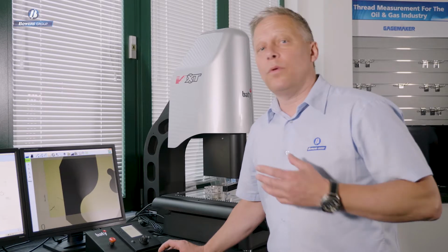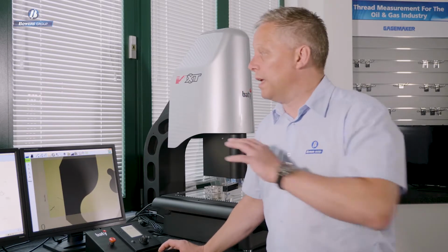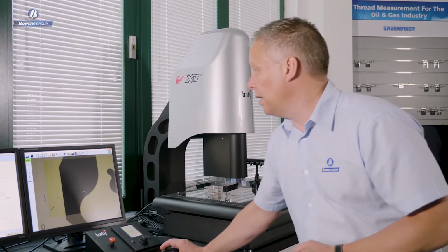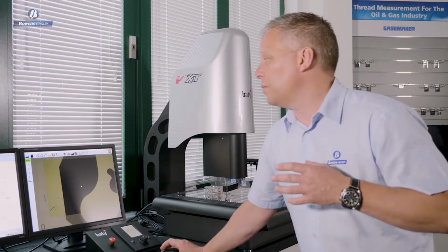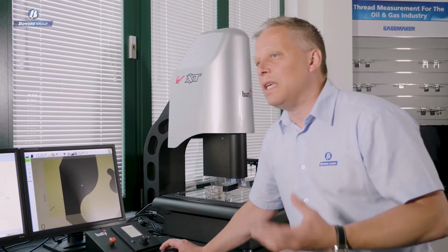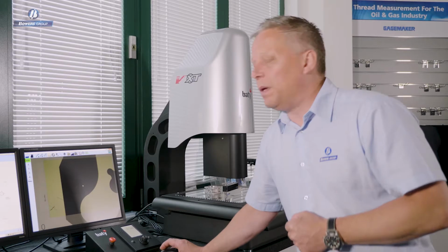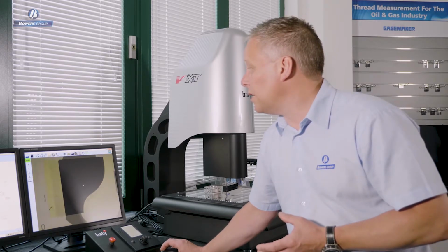Okay, so having brought the DXF in and made a best fit calculation, we get this visual report that all points are in tolerance. That's great. The problem with camera-based systems in the past has been the limited field of view means that we can't see what that overlay and image fit looks like. The big advantage with the latest generation of Fusion software is that we can stitch our images together.